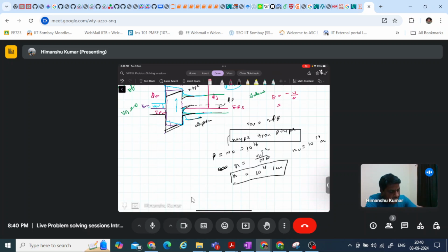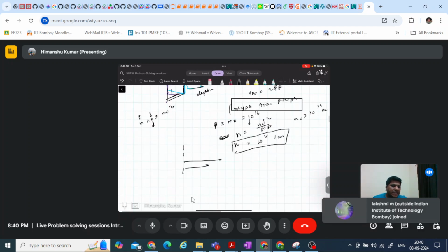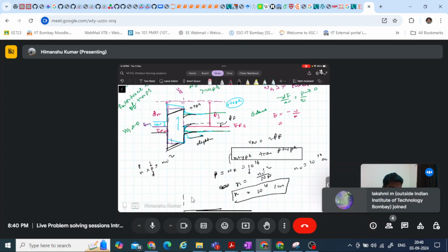If you deplete the holes from the substrate, moving them from the interface into the bulk, then P will go down and the electrons will correspondingly increase. So you are depleting the majority charge carriers and generating minority charge carriers.